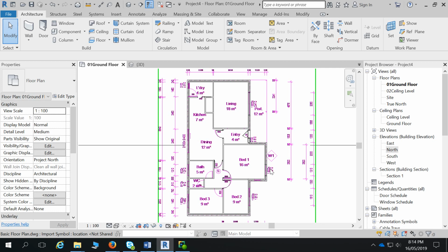If you had your own family, you can just add the sizes to the standard sizes. You want to make sure you duplicate it though. If you don't duplicate it, you've got to change that one window to different sizes. So you duplicate so you have different types of window. Yeah, just different sizes. No, duplicating just creates another type. The duplicating is an easy step to this too.